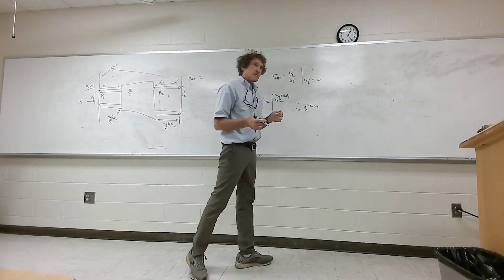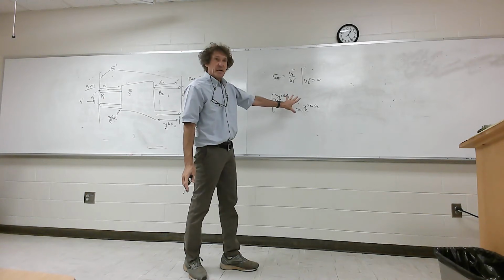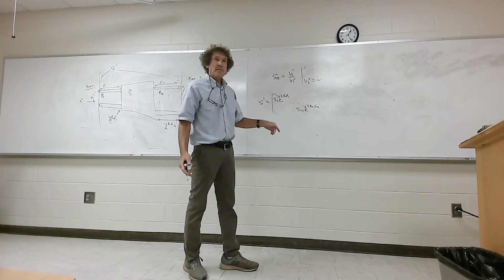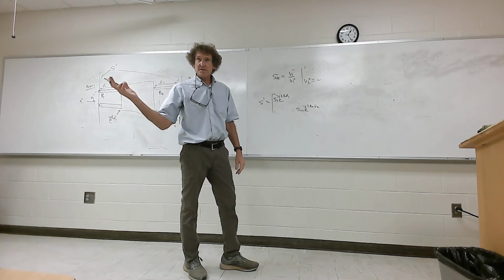Usually beta 1 and beta 2 are the same. Now, what you're doing is this. You're going to measure these things, and then you're going to extract the actual S parameters by getting rid of the effects of that cable, the phase shifts. Y'all follow me in this class?